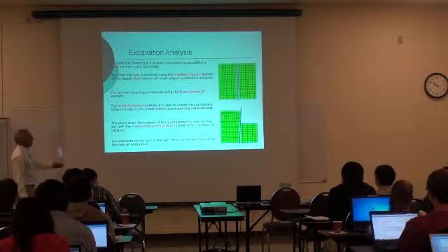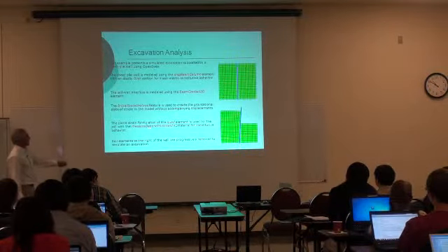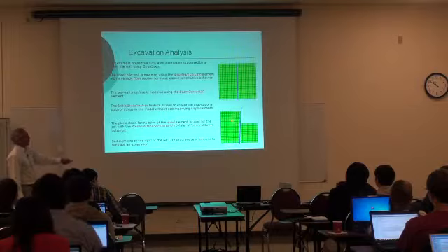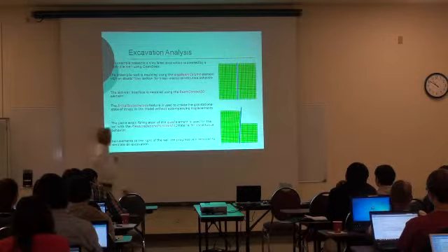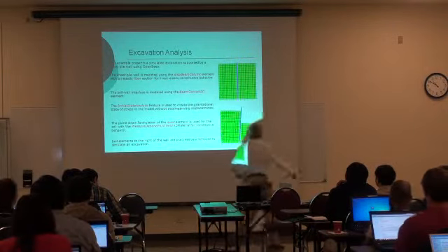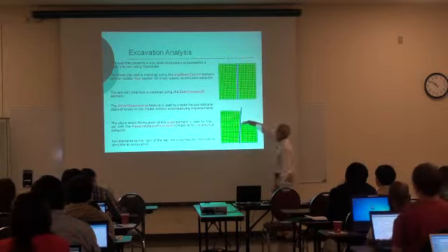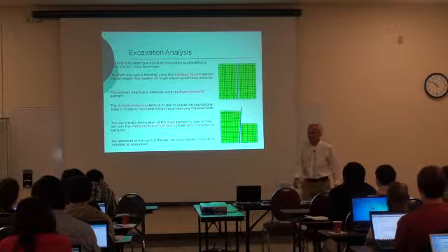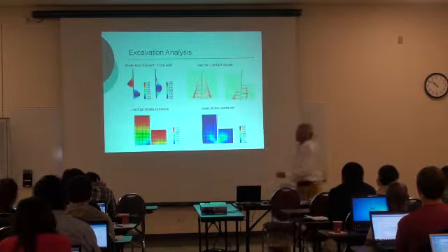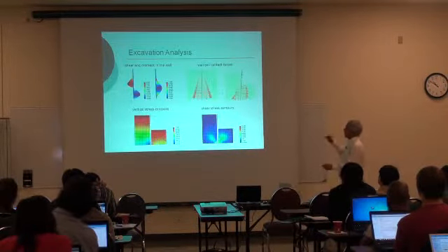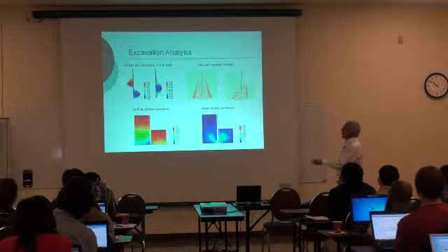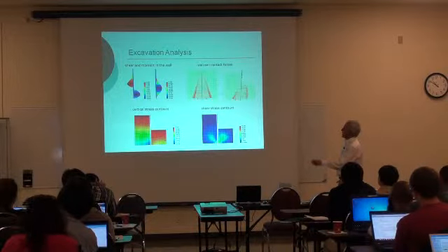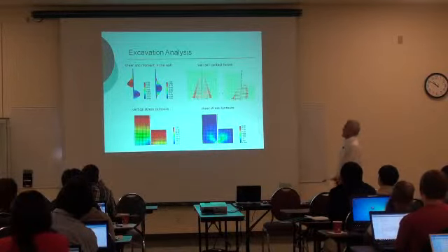We use the quad elements for the solid. We use the pressure-dependent multi-yield to capture the nonlinearity of the soil. And the soil elements to the right of the wall were removed or deleted in OpenSees as we did the analysis. So if you do that, for a particular situation like this, you get the moments, the shear demand, and you get also the moments.